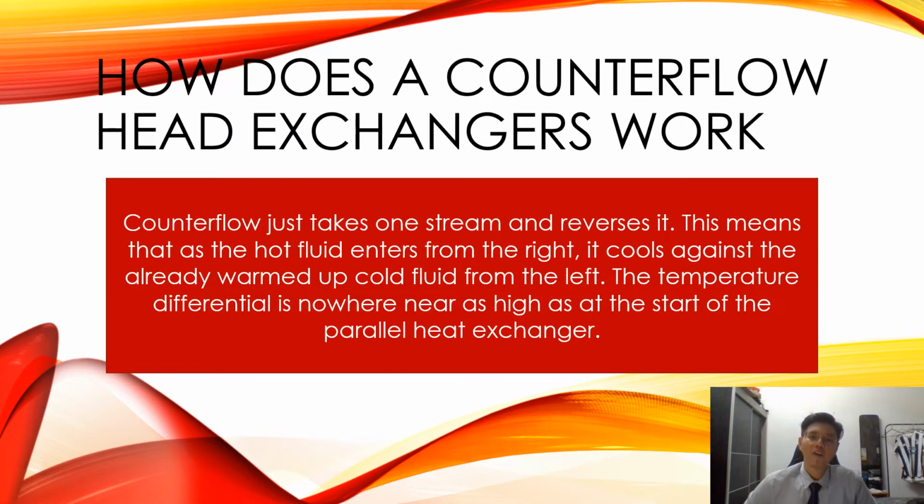How does a counterflow heat exchanger work? Counterflow just takes one of the streams and reverses it. This means that as the cool fluid enters from the right, it cools against the already warmed-up fluid from the left. The temperature differential is nowhere near as high as at the start of the parallel heat exchanger.